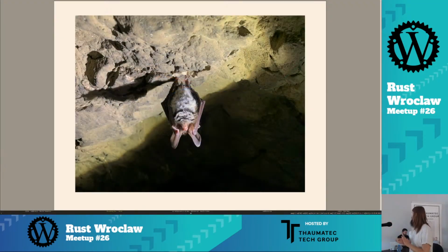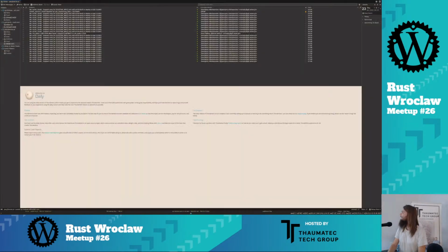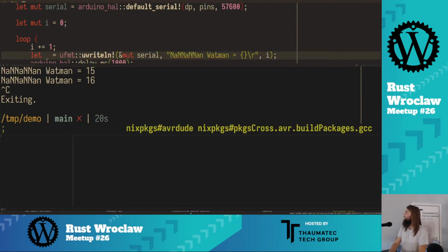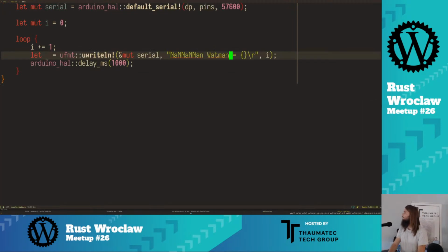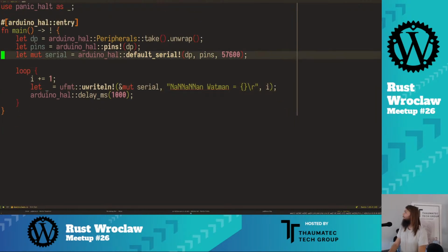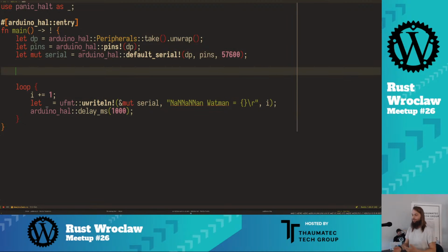Could you open the code back again? Well, opening code will be up to me. Okay, so we are back in the code, and how to start from now. So first we'll need access to 2 pins, because one pin is the pin that we will set to high to notify the device that we want it to start measuring, and the second pin will be the answer from the device. So I will just copy paste the names as I have written them on the board.